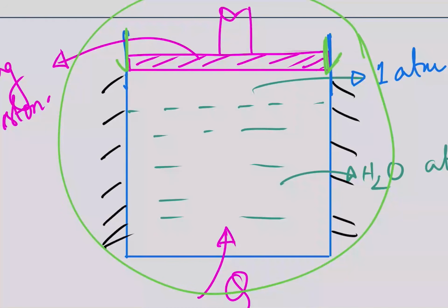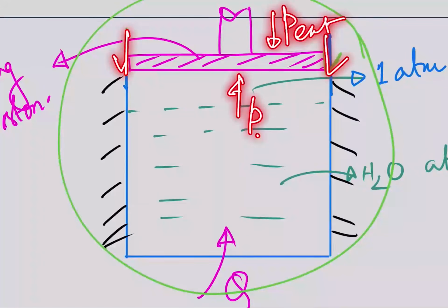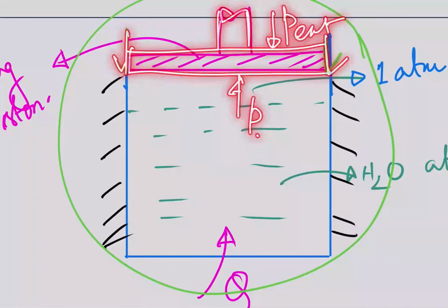What I was asking you is that if I have friction here, then the process can still be quasi-static, because quasi-static means the process has to be very slow, which you can always do. But if there is friction, you cannot write that P external is equal to P internal, because if you now draw the free body diagram of this piston, there will be friction forces.